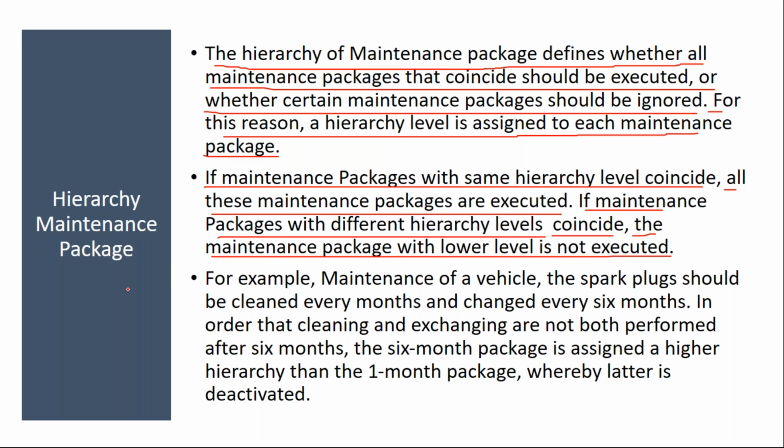Okay, I'll tell you a real-time example. Let's say you are doing maintenance for a two-wheeler vehicle. Now the criteria is the spark plug should be cleaned every month. Every month they have to do maintenance of the two-wheeler and clean the spark plug. Now these spark plugs should be changed after every 6 months.